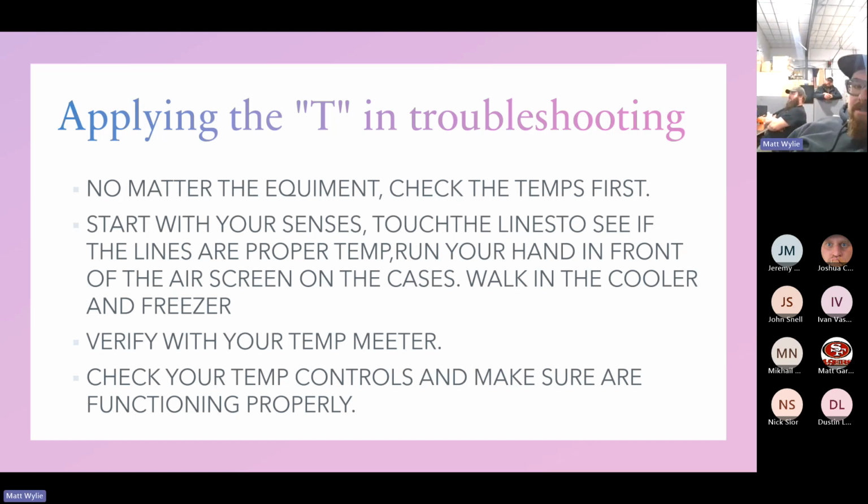Touch the lines. Like saying beer can cold or soda pop cold, it has some point to it. You can still touch it and tell if it's in that temp zone by feeling it. Oh yeah, it's okay, it seems to be working. Then gauge up afterwards. If your discharge line is hot enough to give you a blister, and if it's not hot enough, then you know.